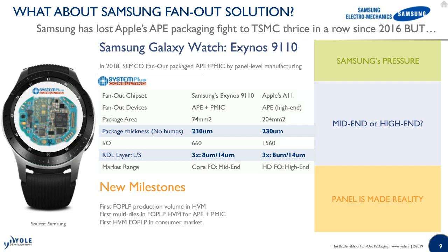Although this is still considered mid-end in terms of I/O, in terms of the package thickness and the RDL line space, it's actually the same as the Apple A11 in the mobile. And just to clarify, the AP in the Apple A11 mobile is actually a high-end device with a lot more I/O, about 3 times more, as you can see at the I/O row.